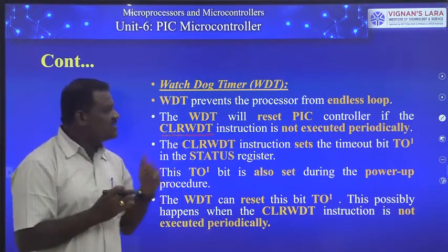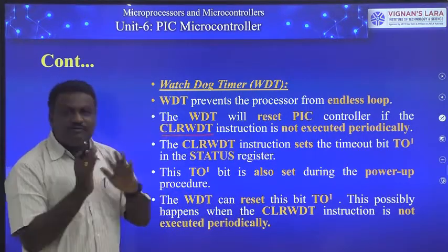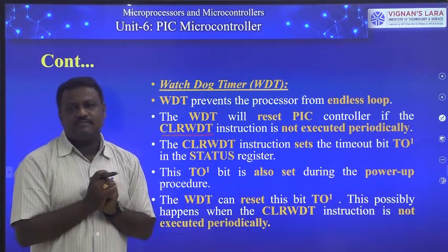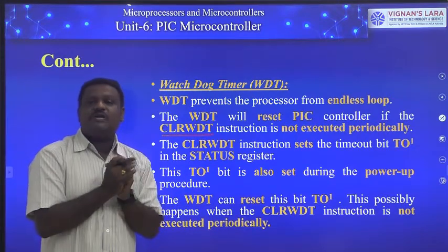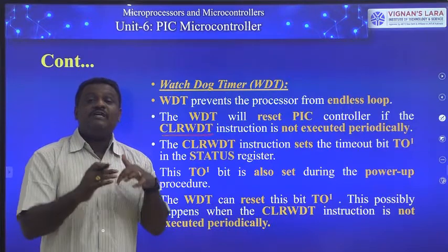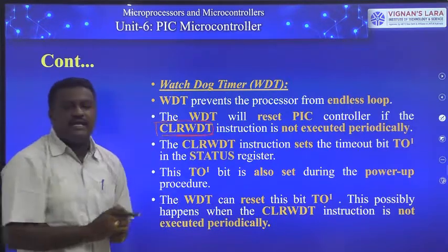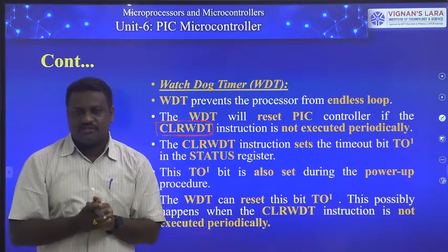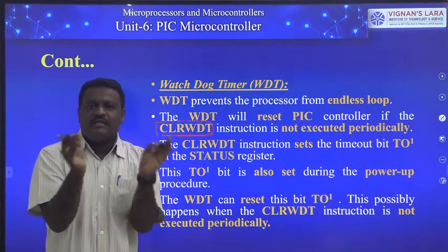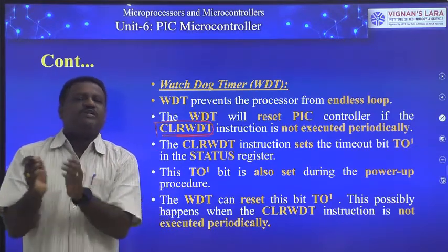So our Watchdog timer will reset our PIC controller whenever it is unable to execute the CLRWDT instruction at regular time intervals.